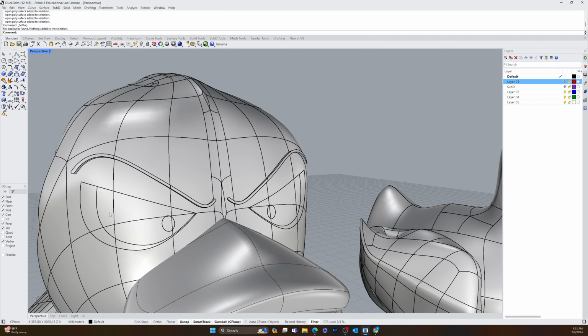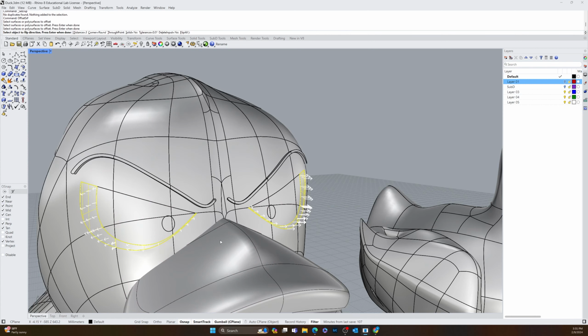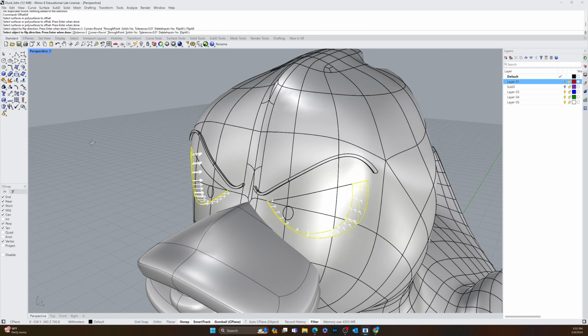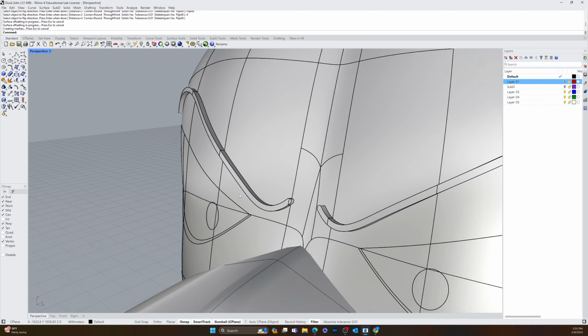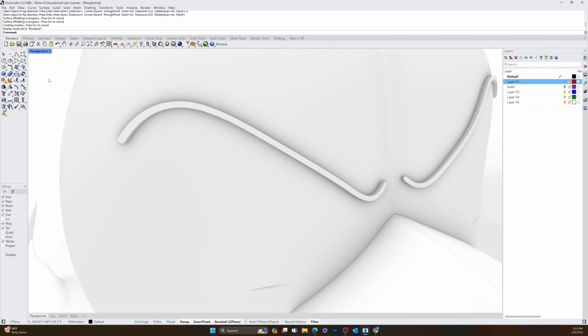So same principle. Offset surface, I'm going to do this surface and that surface, enter. I'm going to flip all, and I'm going to do 4 millimeters, 4, enter, enter. And we don't see any change because we flipped them inside, so you're looking at the outside, okay?